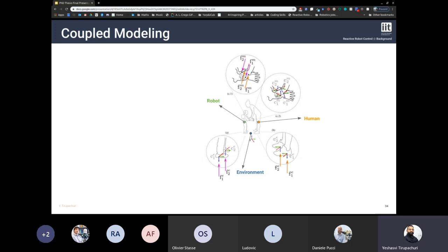Also, this figure highlights the different contact locations that are involved between any of the agents, between the human and the robot, and the agents and the environment. Thanks to the consideration of our human model as a rigid multi-body mechanical system, we can now consider the equations of motion of both the human and the robot together as a combined system.